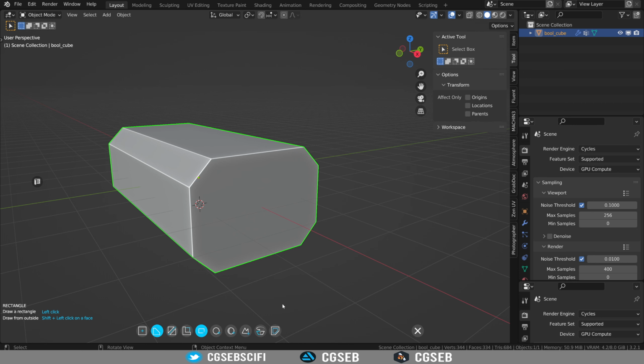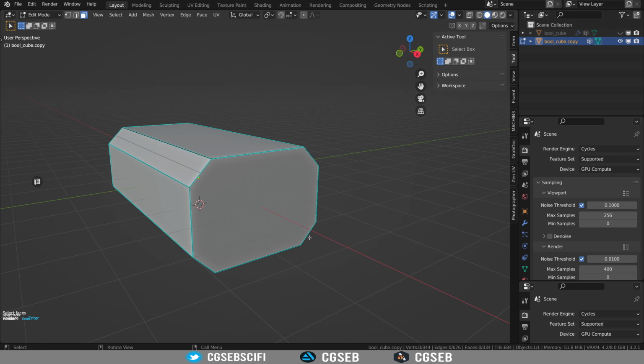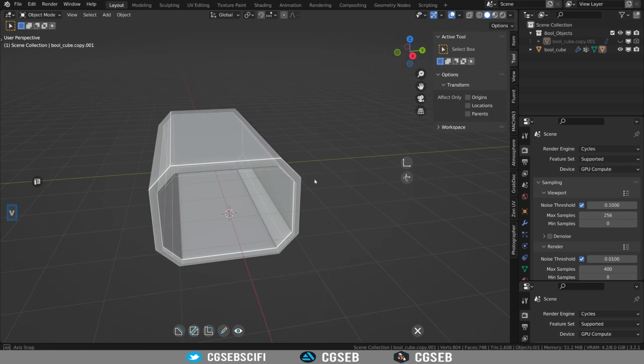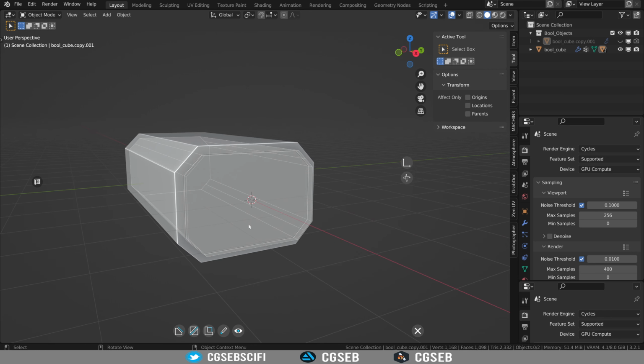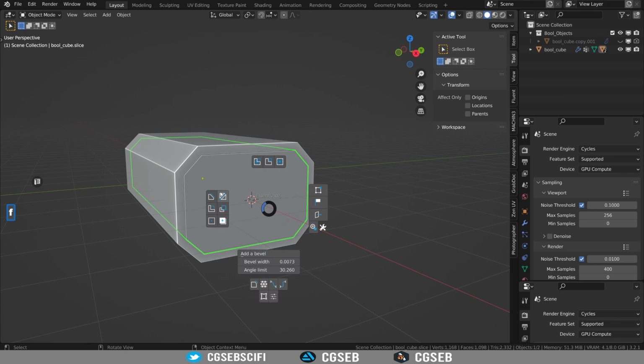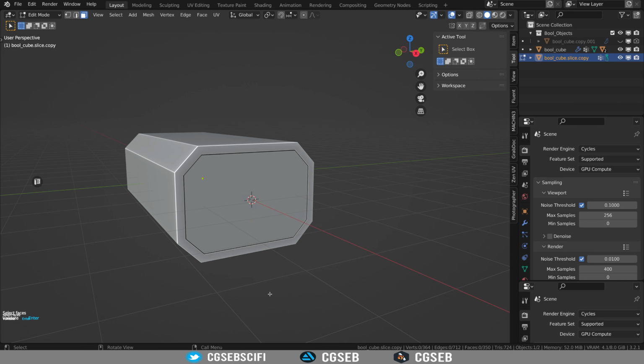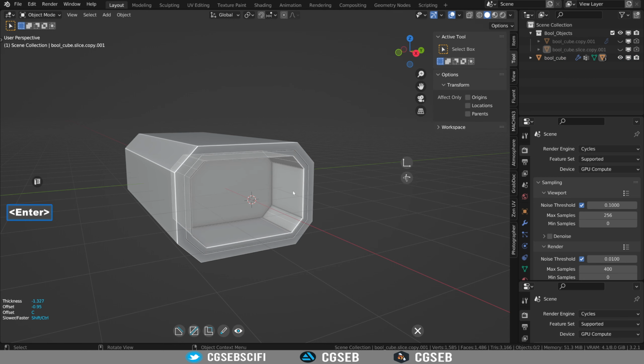So then we're going to click here and then use the face inset tool. If we select this, press I, then we're insetting the face. And then we press Enter and V to go through the object. So we have here the basic wall that is going around the building. So this is a slice for start because we're going to right click and do the exact same thing on this one. So face inset tool, inset, Enter, V.